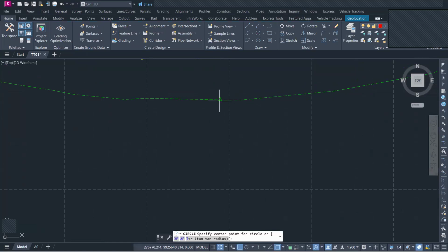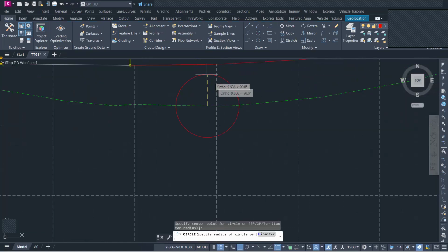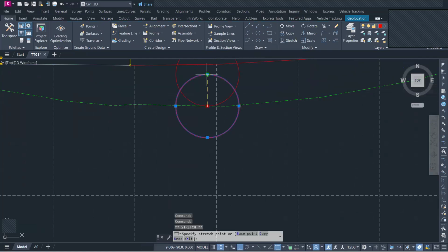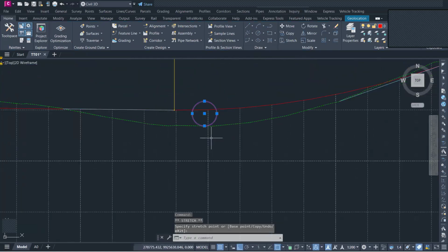So you know this is the OGL. You normally create a culvert, or rather, for example, a circle that has a diameter of what you have calculated here. So this will be 150, 150, that is 300 mm. 300 plus 900 becomes 1200, plus 50 becomes 1250.